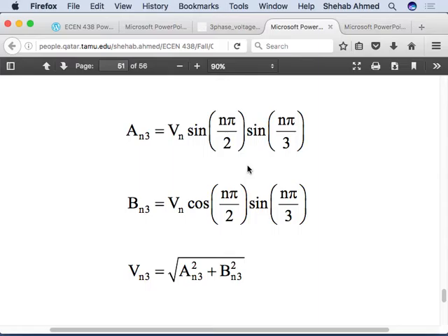Harmonic resonance studies is another kind of study you conduct in a power system. You want to make sure that your system is safe at various harmonic frequencies. So you're switching, for example, at a certain frequency. You're expecting there should be harmonics in your power system at that frequency. So you build a model of your power system and excite that model with that specific frequency that is in your system. What will happen? You look at that system. Okay, are currents going to increase very much? Am I going to get high torque pulsations in the generator? So that's another study that you conduct. Right? So there are various studies that you conduct in a power system when you're designing one.